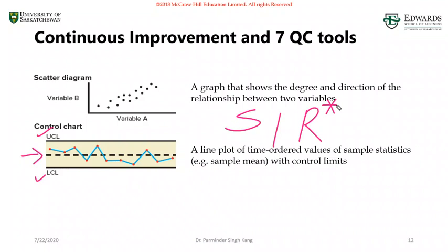On the other hand, if you have a data point, let's say here, outside the control limit, either the upper control limit or the lower control limit, that is due to a special cause variation. Sometimes we call it assignable cause, which means the variability which happened in this process can be assigned to a specific instance, right? We will not go through how to determine the upper and lower control limits at this point. That will be part of the next chapter, where we set up the control limits for control charts. But at this point, the only idea here is how control charts work, right?